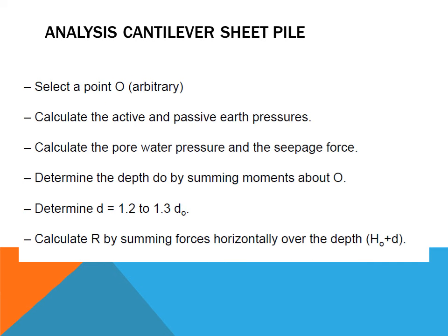Here are the steps involved in analyzing the sheet pile. First, select a point O. Then we calculate the active and passive pressures accordingly. If there is any pore water pressure, surcharges, or seepage forces, then we should include them in the pressure diagram.